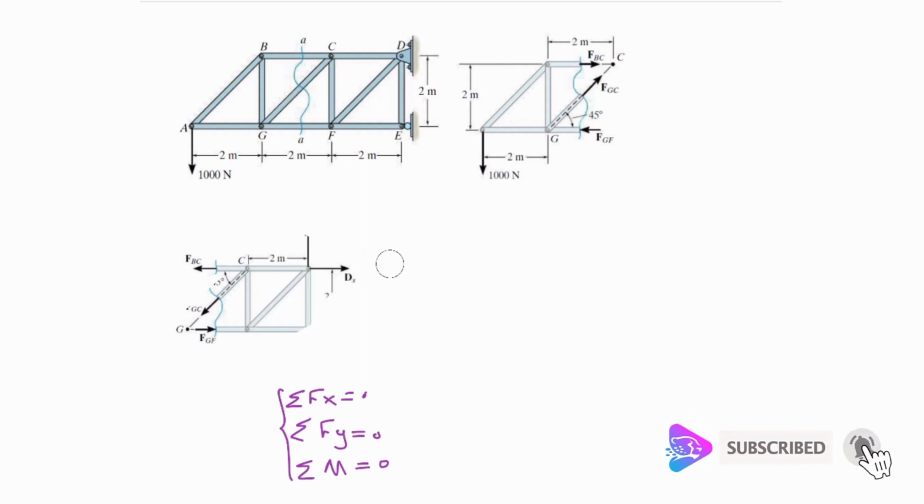The thing that we need to be careful about is the directions of the forces. Here it's completely arbitrary, you can put whatever direction you like, but when you are cutting through something like this, and you put the force of BC like this on the left part, you need to put exactly the same force, meaning the same magnitude but with reverse direction, on the other side.